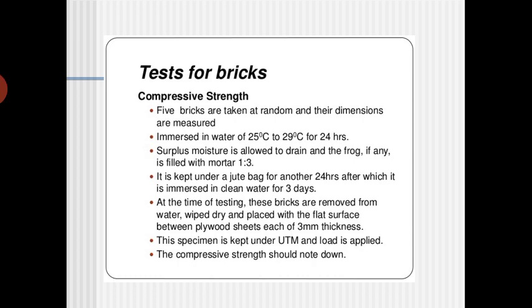How are we going to conduct this compressive strength? Of course, tensile and flexural strength are very important, but normally we will not conduct them here. Why? Because compressive stresses are more on the walls of any building. Normally the tensile stresses are very less, so that is why we will not conduct the tensile strength. So the first one is compressive strength. Then how are we going to conduct it?